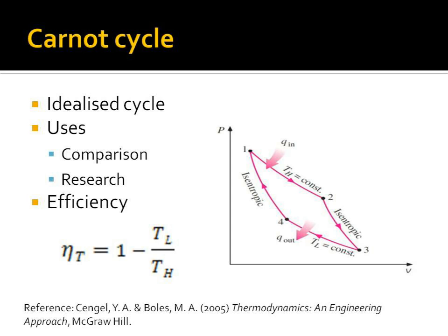Starting off with the Carnot cycle, it is an ideal cycle. And for those reasons, an engine based on the Carnot cycle is unachievable, so its uses are strictly for comparison and research only. The Carnot cycle establishes a formula which is known as the Carnot efficiency, which is 1 minus the ratio between the lower temperature source and the higher temperature source.